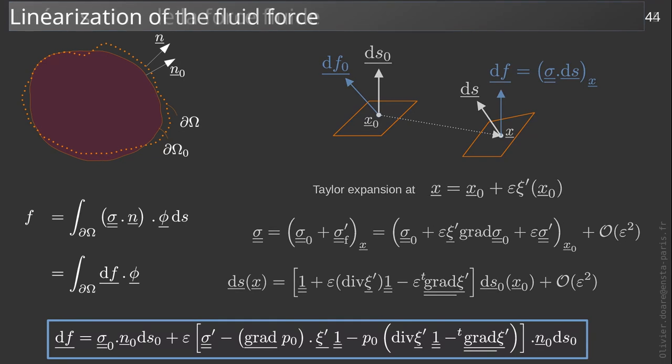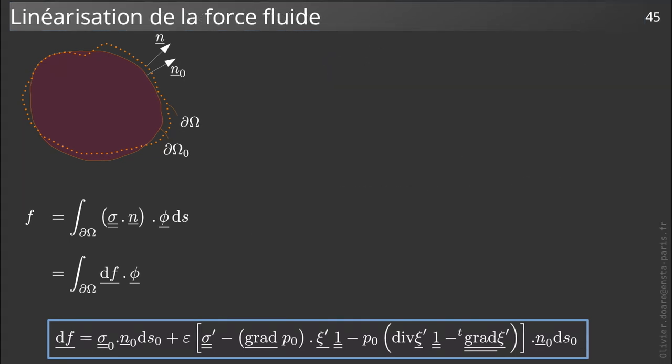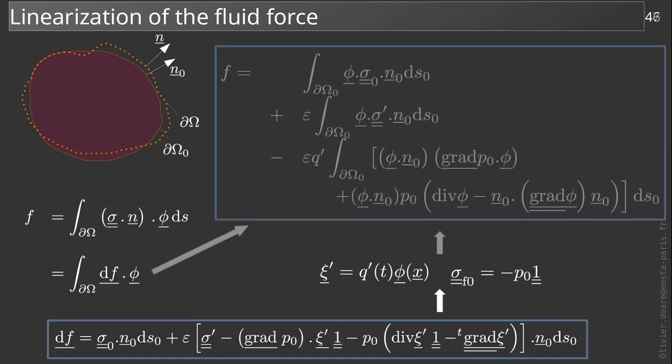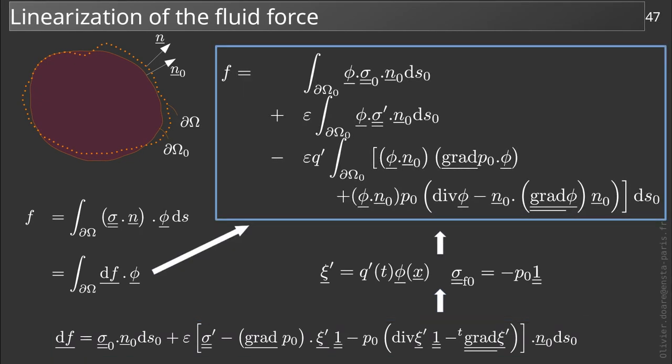Let us now particularize df in the case of a single-mode dynamics in a hydrostatic pressure field P0 and project this on the considered deformation mode. The fluid force then takes this expression, which will be very useful to us because it only involves integrals on the interface in the reference state d omega naught and fields defined at x0 in the reference fluid domain.